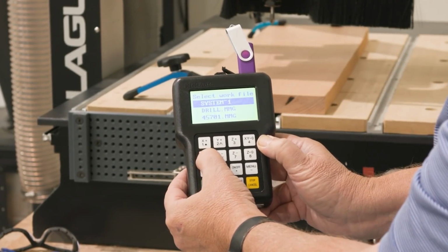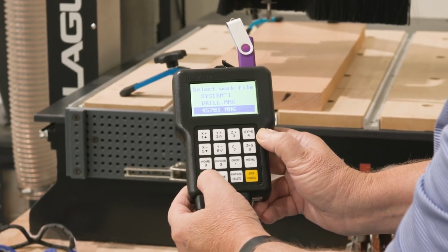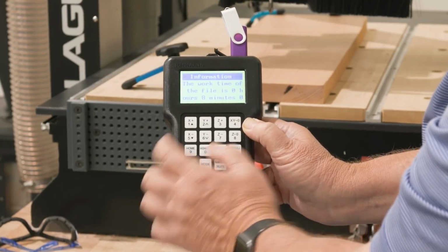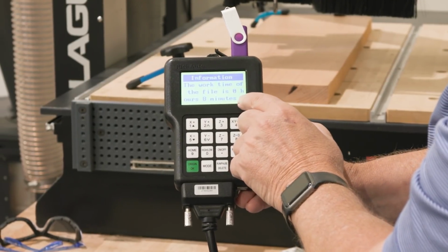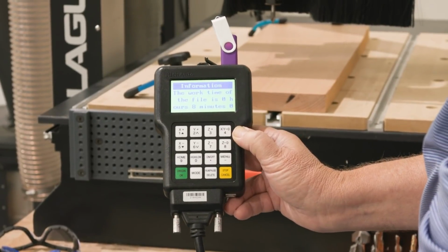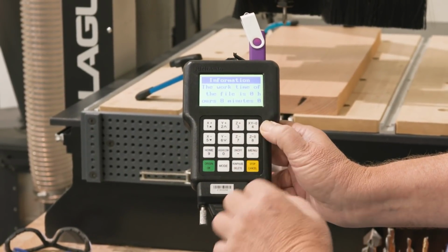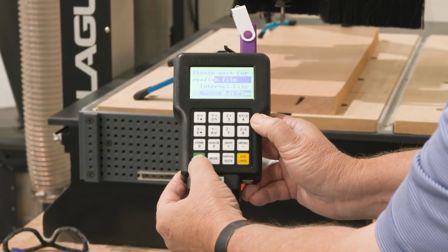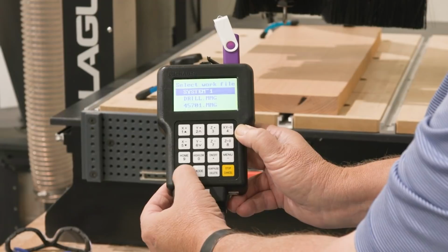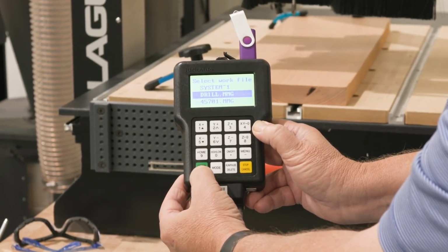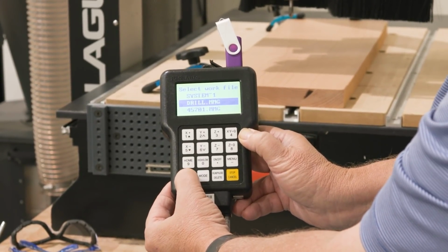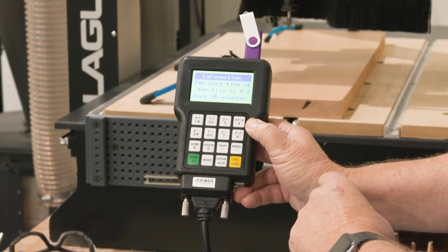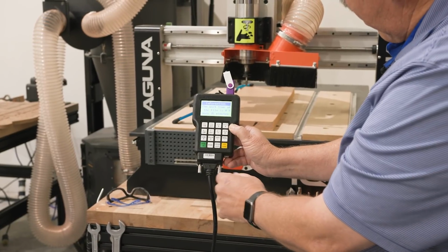So the first one we're going to run is 45701, which is our V bit. So if we check that, you'll see that it says this is supposed to cut 8 minutes based on the fact that we're reading the G code, which is the more accurate way to do it. Hit stop cancel, hit check pro time again, hit U disk again, and then we'll go down to the drill path, which is the longer path, hit OK, and the machine says we should be able to cut that in 35 minutes. Little extra pro tip for you.